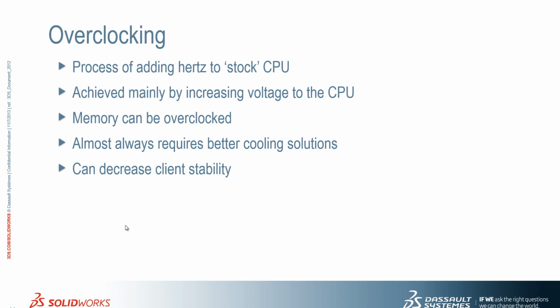But if you do like building your own machines, you may be able to make use of overclocking quite easily. And most Intel chips, for instance, you can overclock by at least a gigahertz without too much trouble. So you can get better value out of your CPU. It does shorten the life slightly, but to be fair, by the time you'll want to upgrade, which may be 2 or 3 years down the line, it won't have run out in that amount of time. It won't damage it. So you can quite easily overclock them and get away with it.